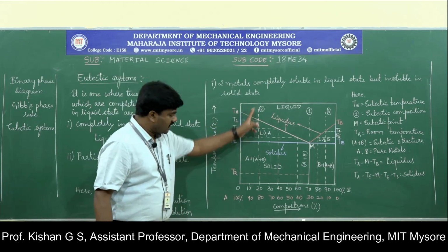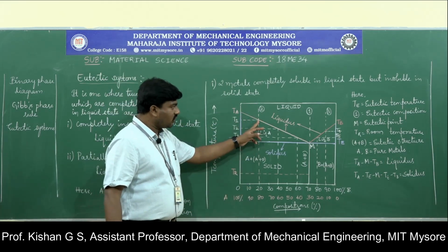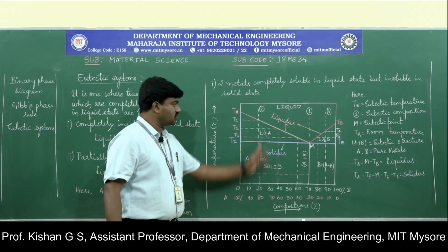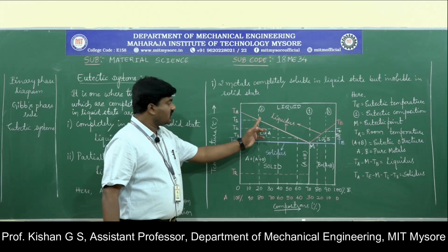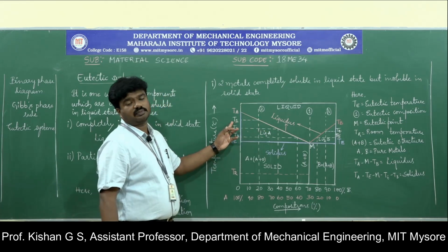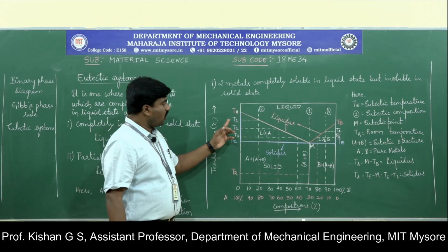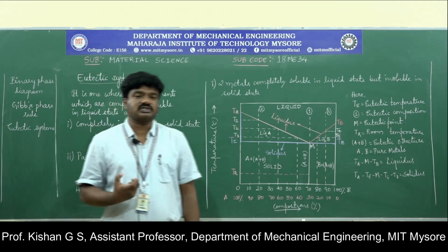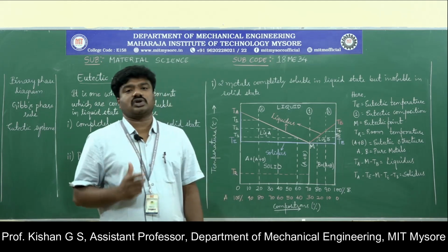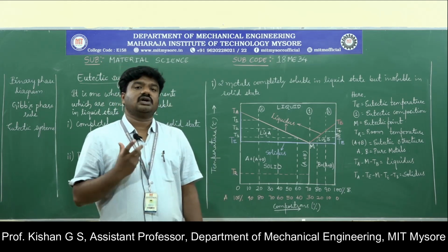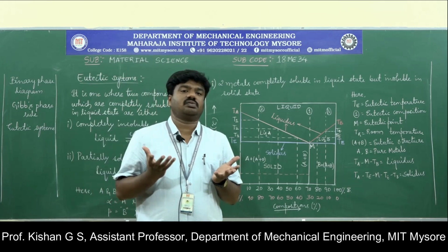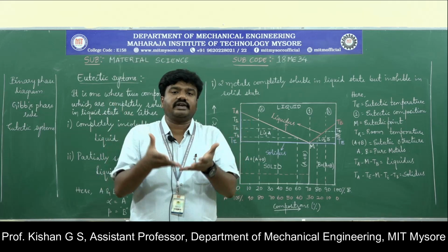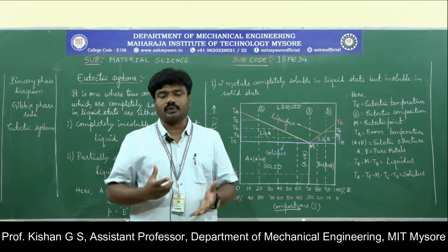With respect to the second composition, the point of intersection where the line drawn from the 80-20 composition reaches the liquidus line, we have taken as temperature T1 degrees Celsius. What does T1 represent? T1 represents the initiation of solidification. As we remember, we heat both the metals to a liquid stage, and once you start solidifying, both the materials converge together to form a solid product.